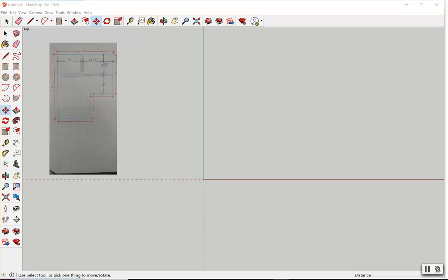When you are beginning to draw the interior model of a building, and you will want to have the accurate interior spaces, then you will need to work not from your exterior walls, but from your inside walls. You will begin drawing the inside measurements, typing them in so that they are accurate, and then from there you're going to use a command known as your offset, which we learned in AutoCAD, to create your exterior wall thicknesses.